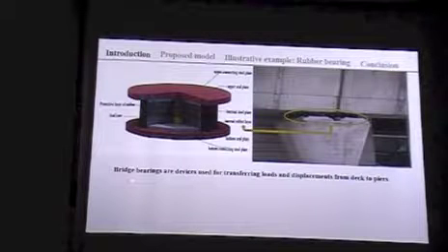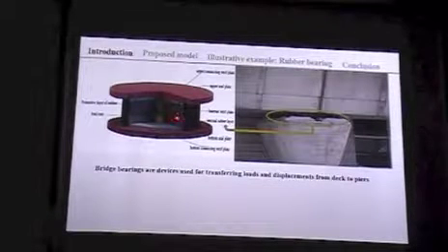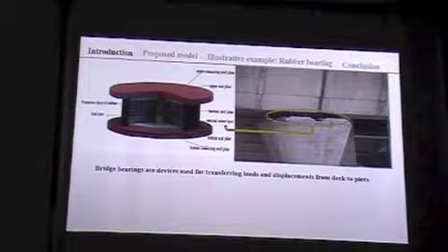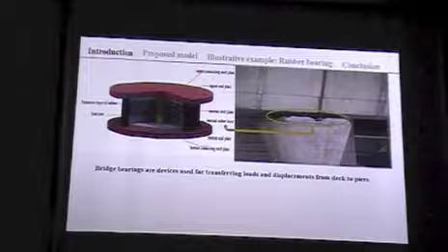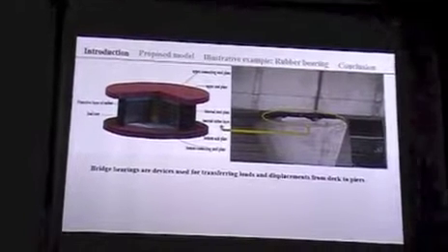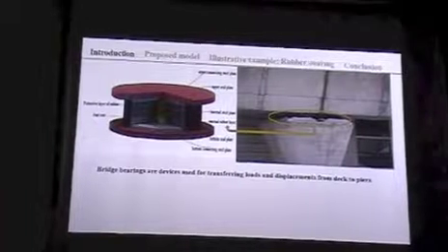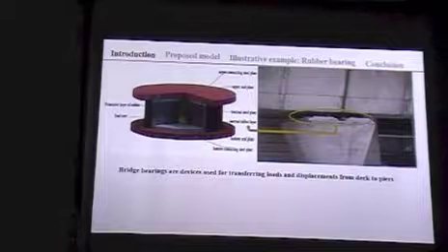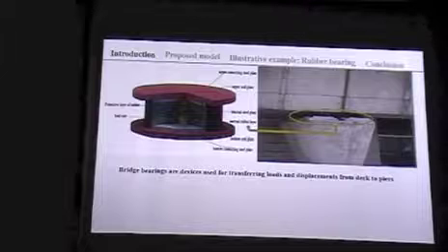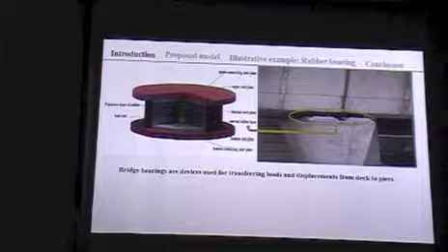The laminated rubber bearings are mainly composed of rubber-like materials and steel, molded as a sandwich material. Rubber-like material is used because of its ability to absorb and dissipate energy without transferring harmful stress, and because it is known to undergo large elastic strains and exhibit a highly nonlinear, hyperelastic behavior.